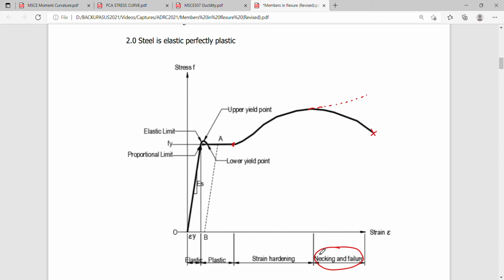Because the necking area is not the one considered in your computation, then of course the tendency for the stress is to drop. But if you consider the necking area, which is smaller than the initial area, then this will actually still be increasing, if not maintaining, the ultimate stress given by the variable Fu.